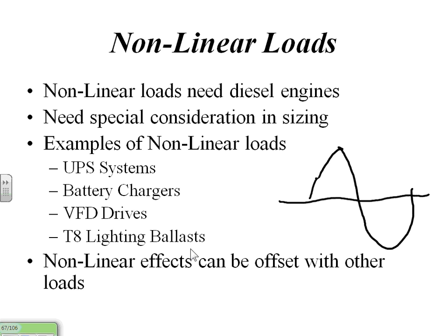If we look at a nonlinear load, you probably know that there are electronic devices, and they're SCRs primarily, that are actually spiking this waveform. If we were to look at it on a scope, we'd see these little notches all over the place. And that's from those SCRs firing on electronics. That's a bad thing for gas engines. And this is only by personal experience. Diesels react better to loads.